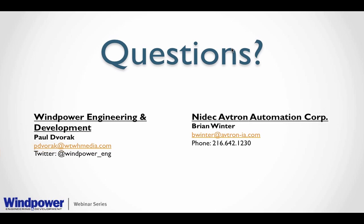Most people don't ever need or use those kinds of resolutions. More commonly it is 1024 pulses or 2048 pulses per revolution. Nice binary numbers left over from the 1970s that, again, control engineers have been using for many years. So magnetic encoders, by and large, can reach the resolutions that are required and honestly quite beyond what's really needed. Okay, very good.